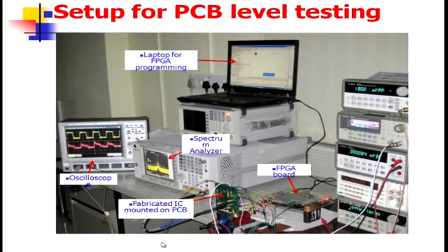And this is the test board. What I said is that I am using a 9-volt battery divided by a voltage divider, because the line noise sometimes disturbs your measurement of noise and signals. So you can use a battery. I am going to have a Faraday cage and line filters, but at that time we used a battery to power my chip so that no line noise comes to the system.